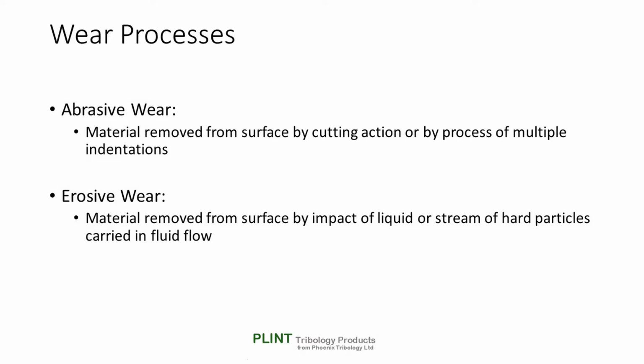Abrasive wear occurs when material is removed from a surface by a cutting action or by a process of multiple indentations from abrasive particles. This may be an intended process, as in component manufacture, such as in grinding or polishing, or unintended, as may occur in machine operation, such as the wear of digger teeth when working in gravel.